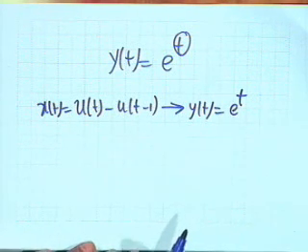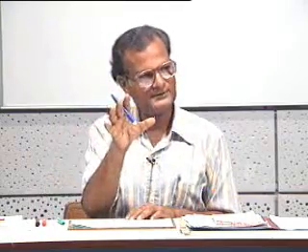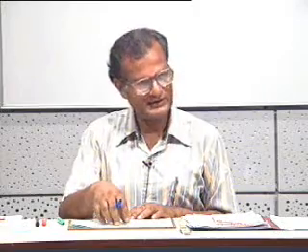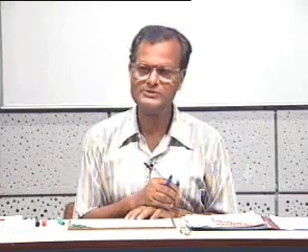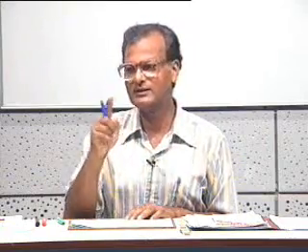Obviously unstable. If under one condition the system output grows indefinitely, that's enough to characterize the system as unstable. Is that clear? On the other hand, you may test under 100 or 1000 input conditions, and each of them leads to a bounded output. You cannot say conclusively whether the system is stable or unstable.